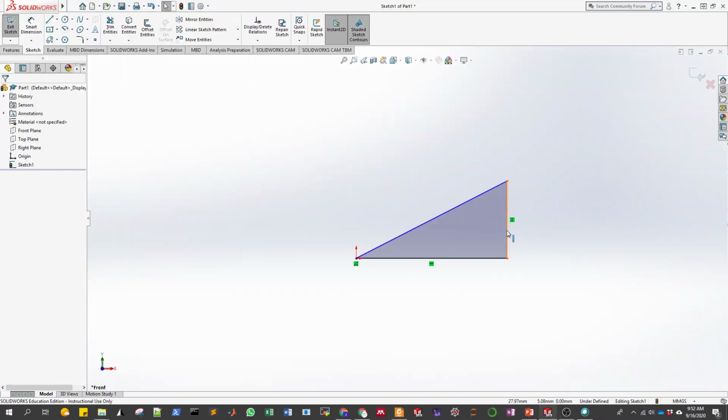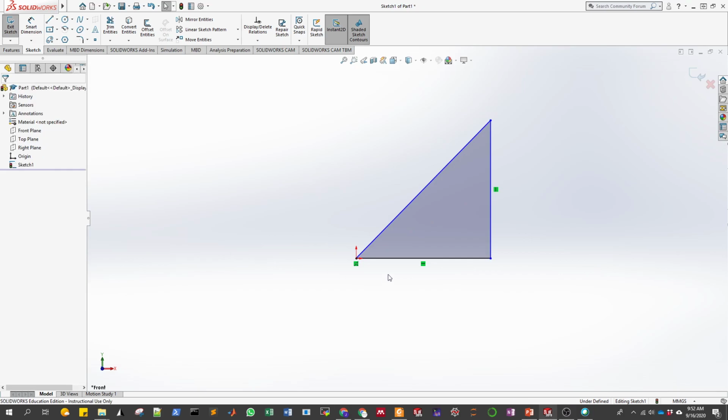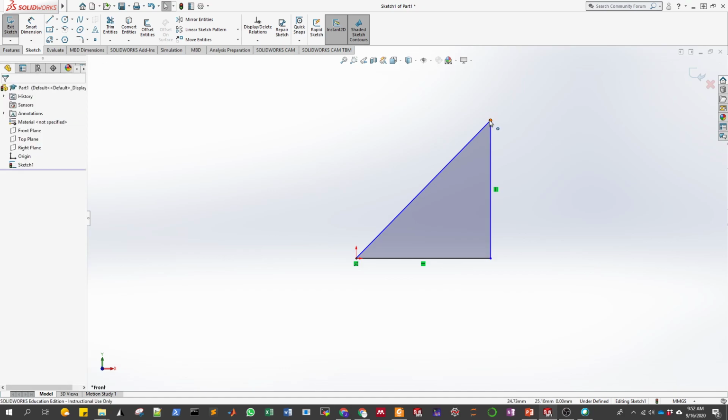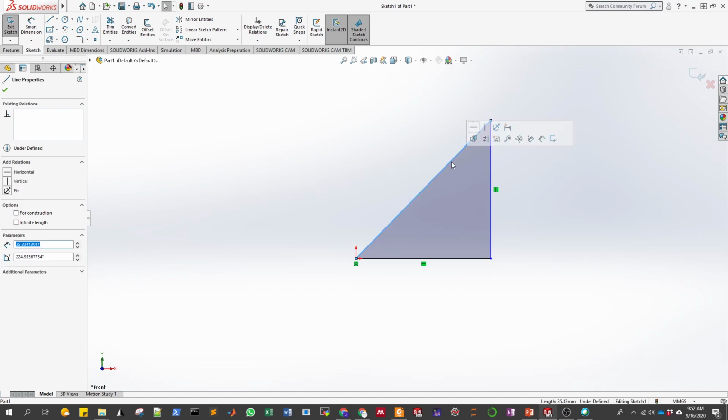Now look what happens if I define the length of these two lines. Just by defining it here. Let's suppose that I want this length to be 25 and also this other line to be 25. You may argue, okay, I defined the geometry of this triangle. Yeah. But again, this is just a provisional length. I can just drag this point around, or maybe I define this length after I already defined the other two,